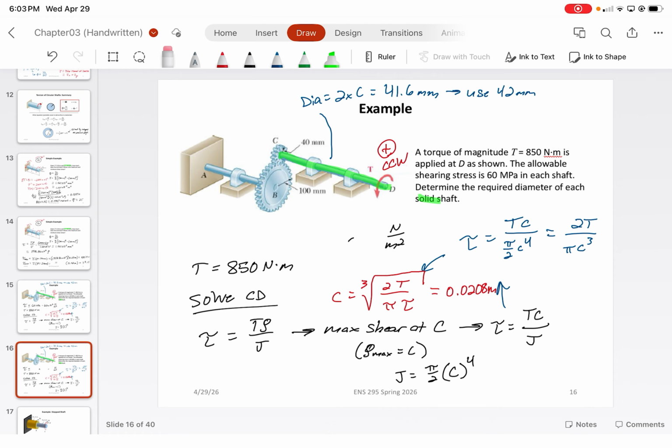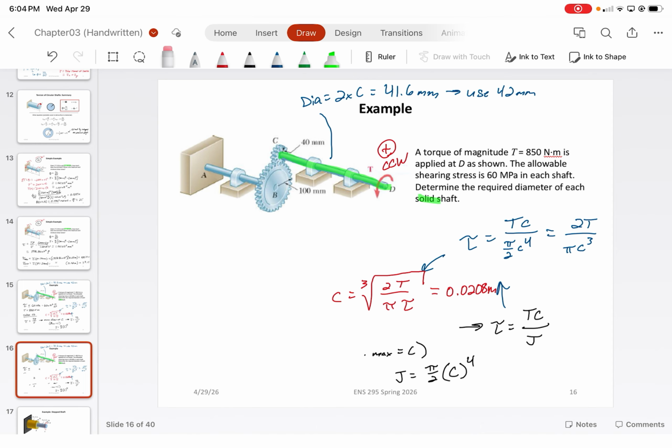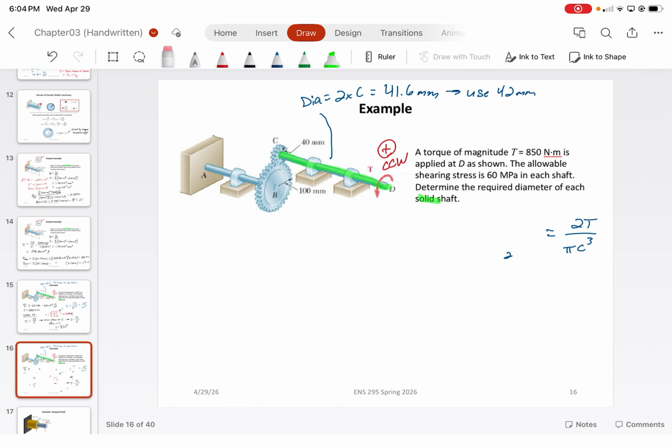All right, but basically, how do gears work? I guess that's an important question that's really required for these types of problems. You multiply by the input radius divided by the output radius. Exactly, yeah. And that just comes from equilibrium, because you're basically saying that the force felt at the teeth has to equal each other, which just conveniently is what you just said. That's what it works out to be.